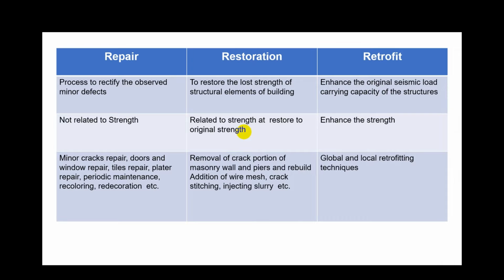Repair is the process to rectify the observed minor defects in order to maintain the aesthetical view of the building, and it's not related to strength. It doesn't enhance the strength of the structure. Some minor cracks in the plasters, reinstatement or repairing of doors and windows, tiles, and some periodic maintenance that can be done, and recoloring works as well as any redecoration works, they fall in the category of repair works.